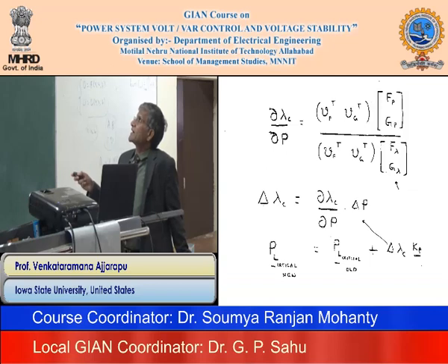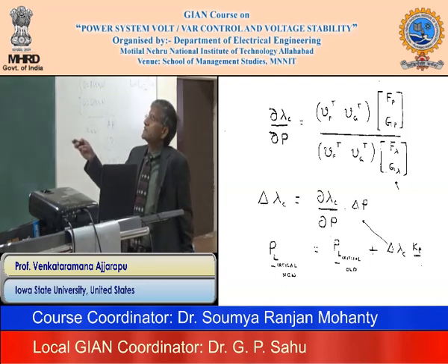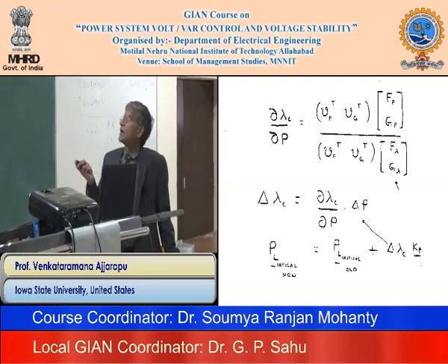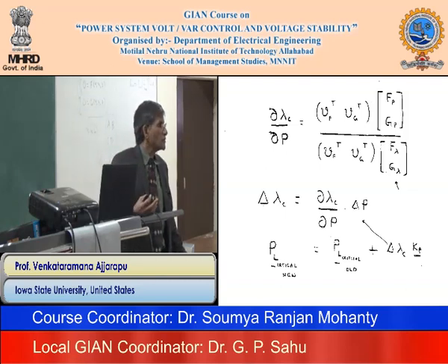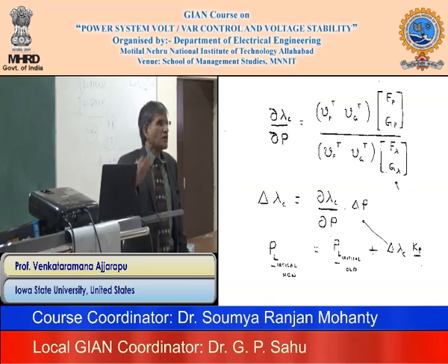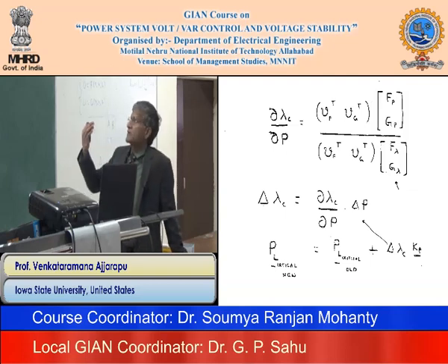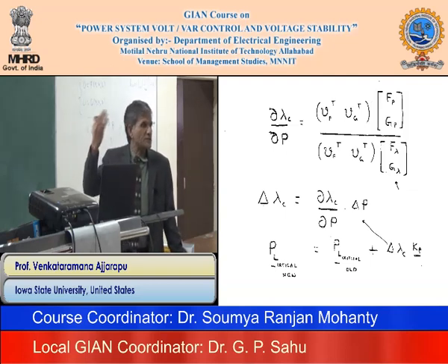So getting this is relatively easy, and these derivatives we can get anyway, because you already know the f function and g function. And the advantage of this is that now I am considering the dynamic part also. In the power flow, that's the importance of the DAE or total equilibrium, because now I can consider the generator side parts and the dynamic side parts also, the gains, if we have SVC parameters and so on.